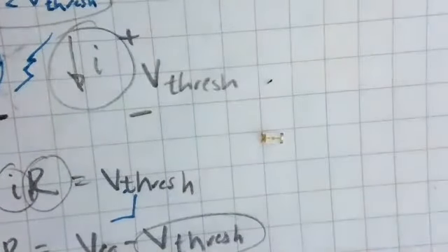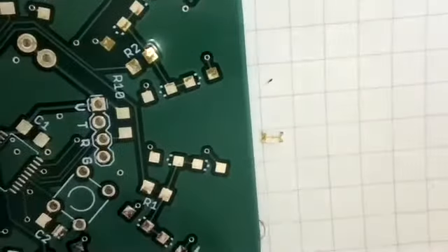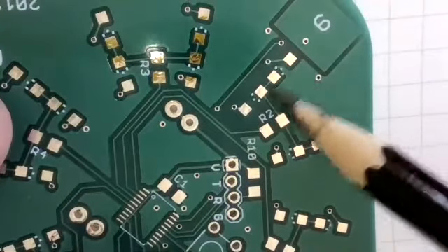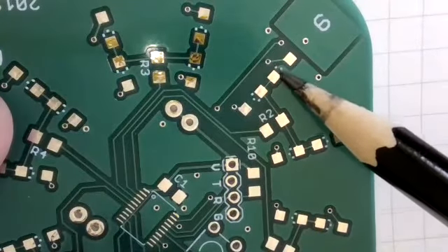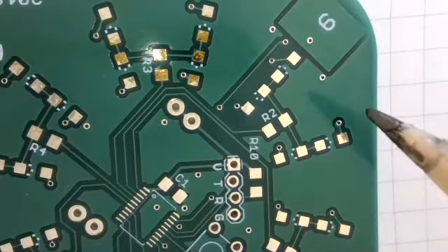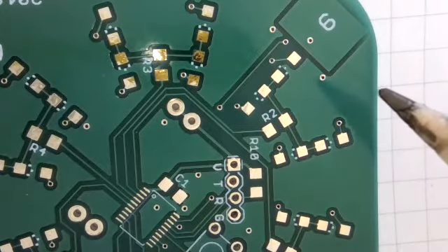So for your lab, you're going to be placing a bunch of LEDs onto this PCB, and you can see the little diagram here, and there's a little arrow that's pointing the direction that current is supposed to flow, from the anode to the cathode, right?